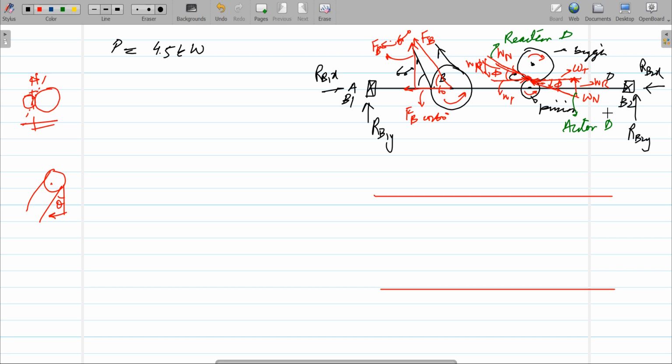As you know from your statics course in your first year, the direction doesn't make any difference. You just have to draw the reactions in whatever direction they are. If your force directions are correct, then your reaction will automatically be correct itself, even if you have drawn the wrong direction.